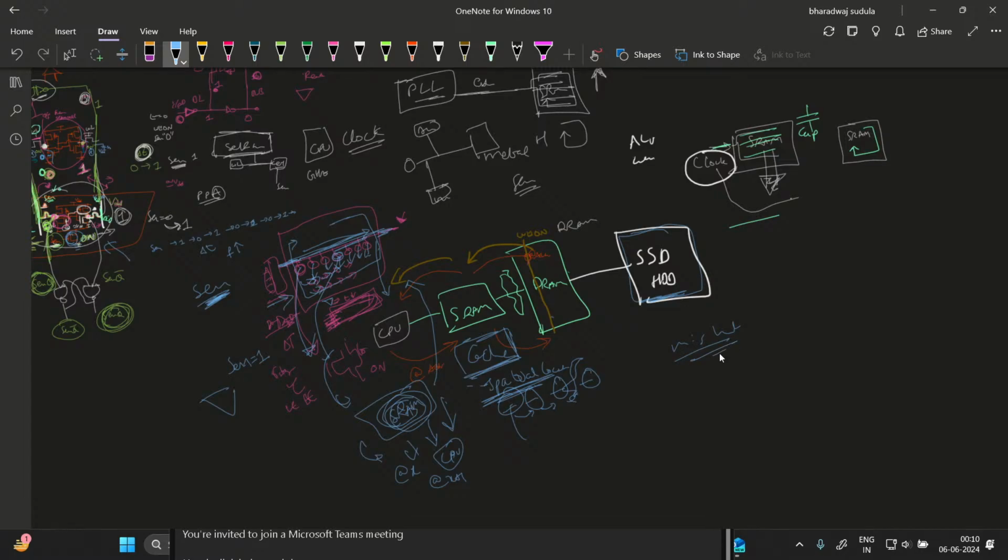While explaining those concepts, he will bring up burst mode. With burst mode, we exploit spatial locality and we place the data in SRAM so that the future addressing locations will have a higher hit rate. We can access it from SRAM itself instead of going to DRAM.